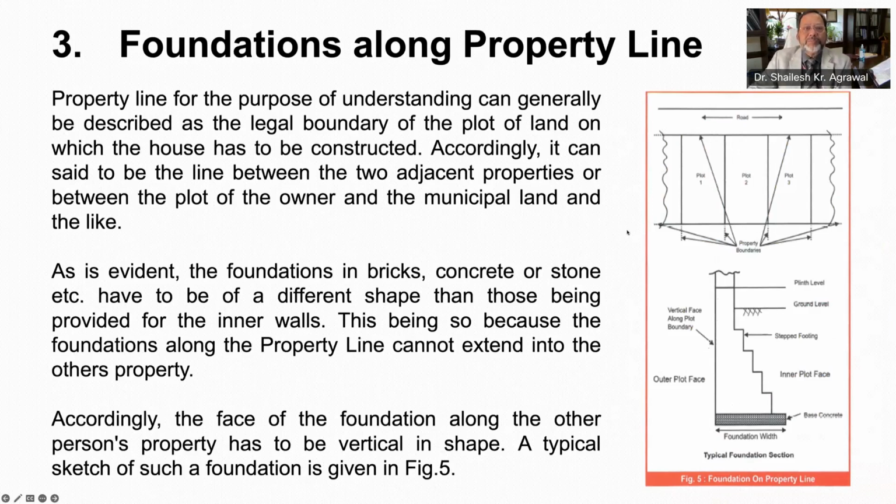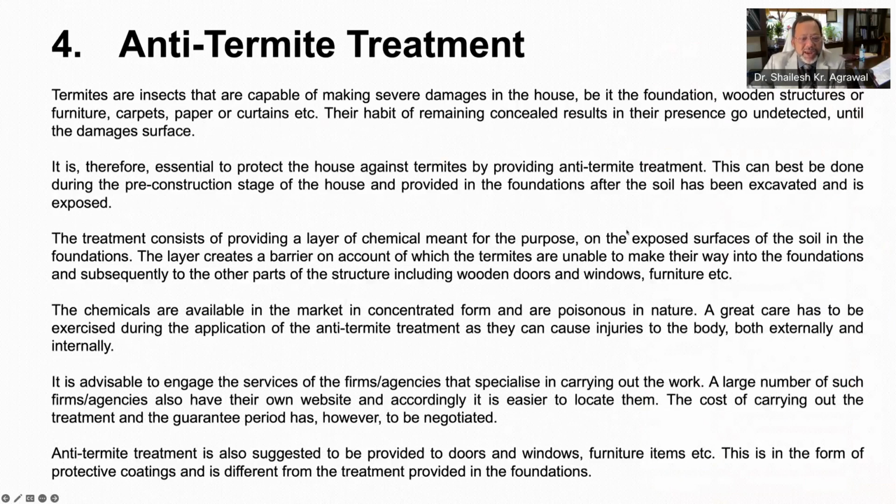Another important aspect while laying foundation is anti-termite treatment. It is essential and comprises providing a layer of chemical meant for termite treatment on exposed surfaces of soil in the foundation. This layer creates a barrier which inhibits termite movement. There are plenty of chemicals available in the market.